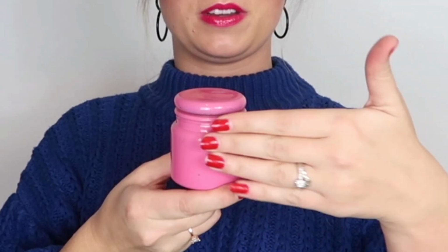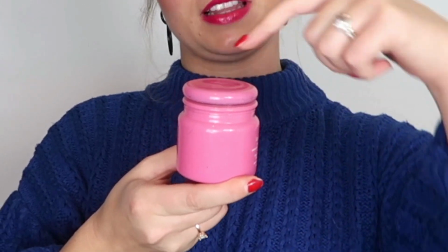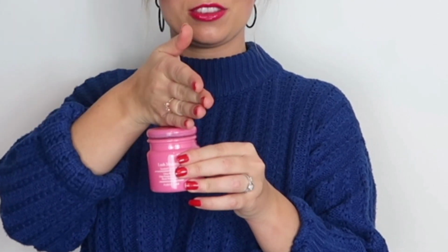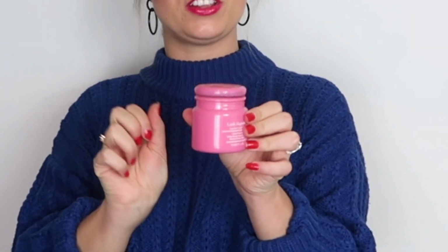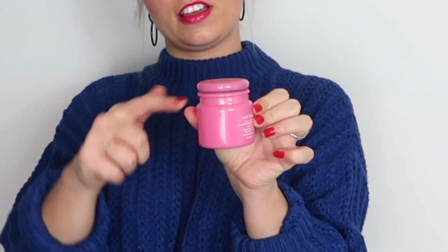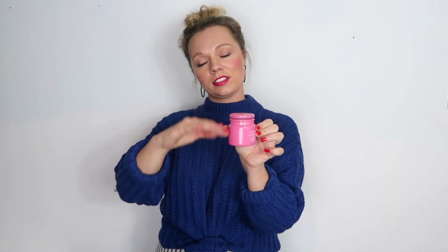So an elevation would be just looking straight at it. We would draw up the lines, we would follow around and fill in whatever finish it is, and put some dimensions next to it as well so we know how high it is and things like that. But with a section, if I had a magic saw, I would actually cut through the object, open it up and show you what it is actually made of and how the insides work, how the material changes and things like that.